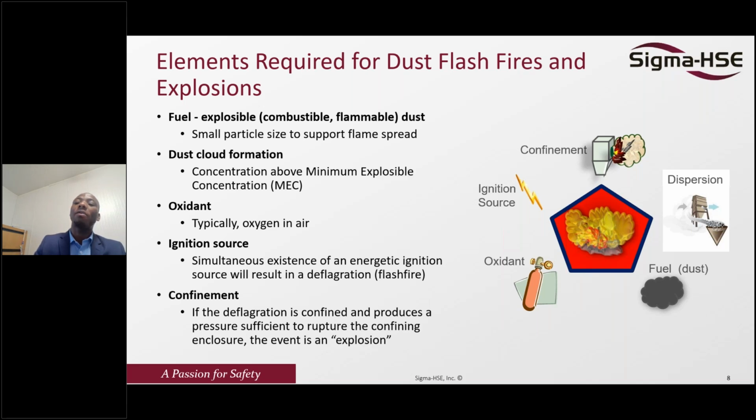But if you don't have a term called confinement or enclosure, this energy release is just going to release to the atmosphere. So if I stay beside this combustion operation, the worst scenario is I'm just going to have maybe a burn, because the energy which is being released is disposed through the atmosphere. However, if I have a confinement, the energy which is being released is going to continue to accumulate, because there's no way to dissipate this energy.